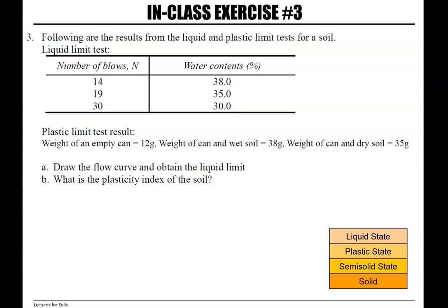So let's go over an example. We have the results for the liquid limit and plastic limit tests. Trial number 1, trial number 2, and trial number 3. For each trial, we have a number of drops and a water content. Also, the result from the plastic limit is provided. The question is asking us to draw the flow curve and find the liquid limit. Also calculate the plasticity index, which is liquid limit minus plastic limit.